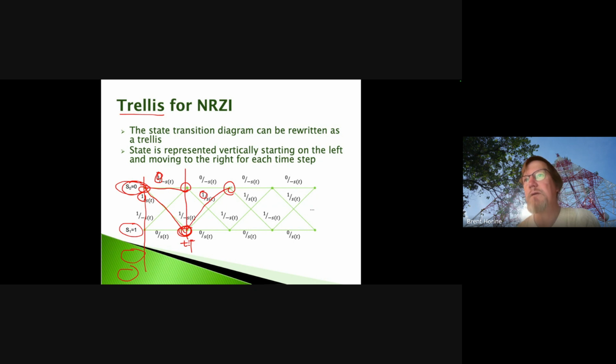So what we see here is, well, I hesitated: do I start here or do I start there to describe this transition? They're the same. They're just at a different time step. If I'm here, I'm in state 1, I get a 1, I'm going to transition to this state 0. That's exactly the same as I drew there. I could draw it right there. So this trellis is essentially replicated at each time step.